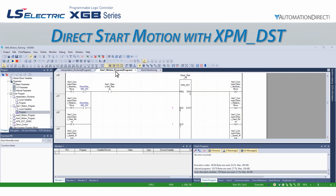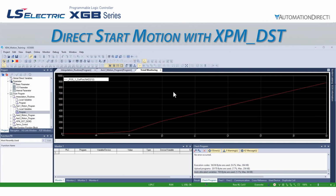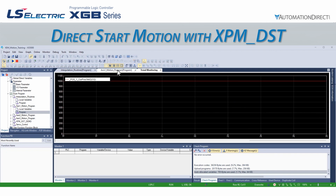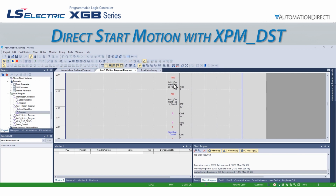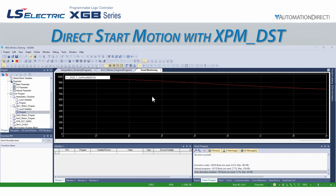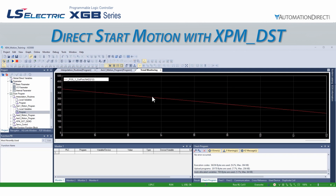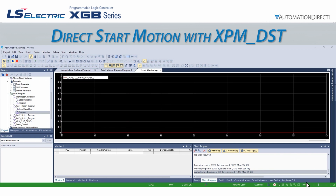If we go back to the Axis 1 motion program, line 90, we can go back into monitor mode, make the Axis 1 command direction absolute move bit true, and then observe the motion with the trend monitoring. We see the X position go to 1000 and hold there. If we go back to the direct start function block and change the target back to 0 and the speed to 100, we can then make the command bit true again, and watch the move with our trend monitoring. We see the axis move back to 0, and it happens much slower since we altered the velocity of the move. The direct start function block is limited, but it is a very powerful and simple way to perform basic single-axis motion with the LS Electric XGB PLC.